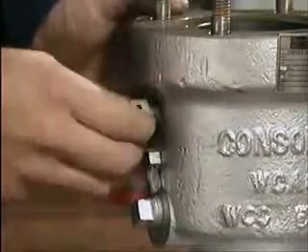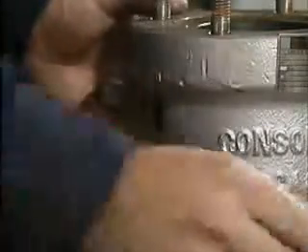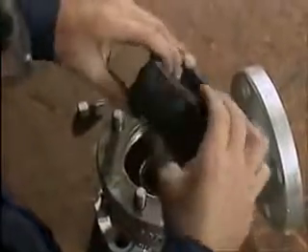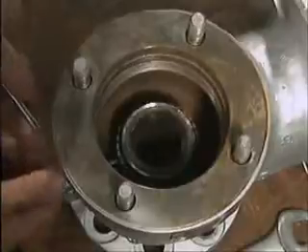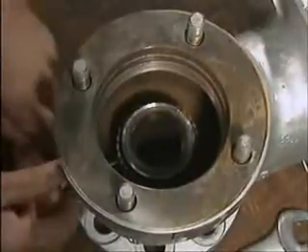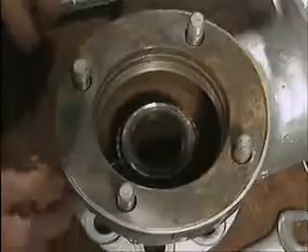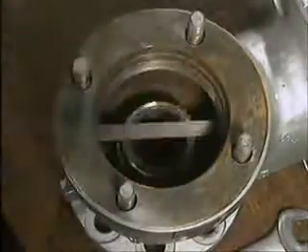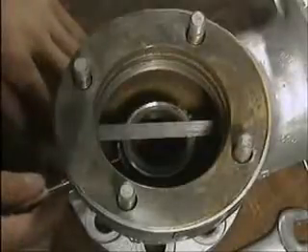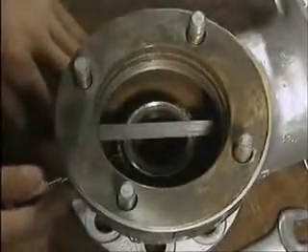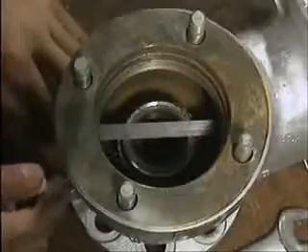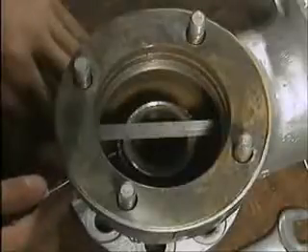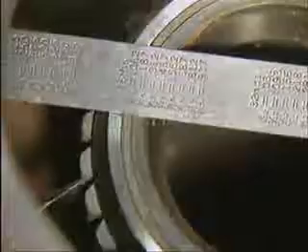Break the upper locking pin free and remove it from the valve body. Then unscrew the upper adjusting ring and set it aside. Now repeat these steps to remove the locking pin for the lower adjusting ring and measure the exact position of the ring. Insert a screwdriver through the lower locking pin hole and unscrew the ring by turning each notch past the pinhole until the ring is flush against the rigid rule that was placed on the valve seat to take the measurement.